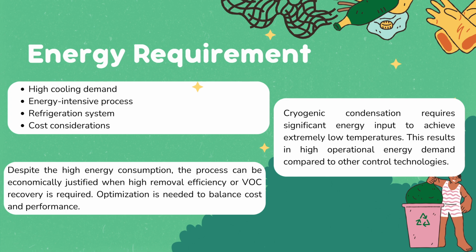Next, we jump to the energy requirement. The cryogenic condensation requires significant energy input to achieve extremely low temperature. This results in high operational energy demand compared to other control technologies. Despite the high energy consumption, the process can be economically justified when high removal efficiency or VOC recovery is required. Optimization is needed to balance cost and performance.